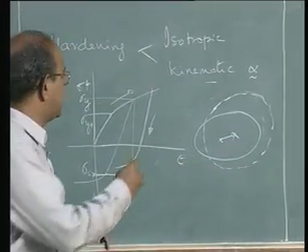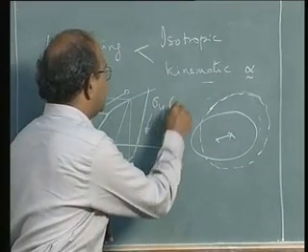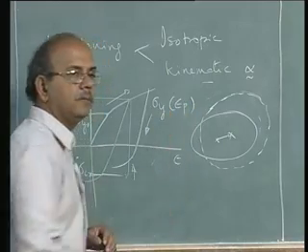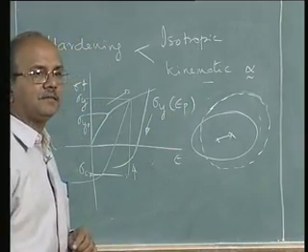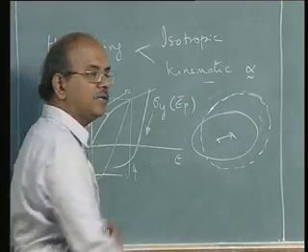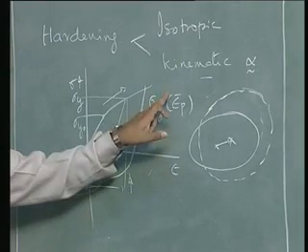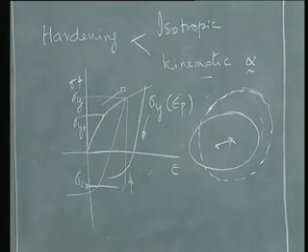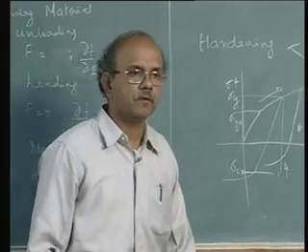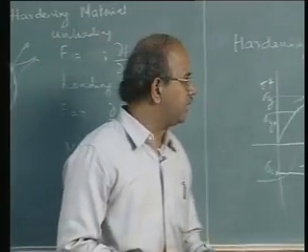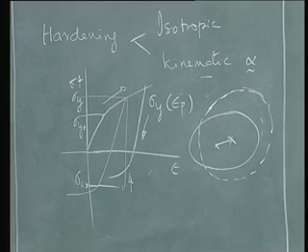Remember that we said σy can be written in terms of ε̄p, and very slowly I would put a bar there. What is that bar? If you look at a uniaxial case, in fact I can remove that bar and write that σy is a function of εp. Of course, it is not right to write σy as just a function of εp all the time.